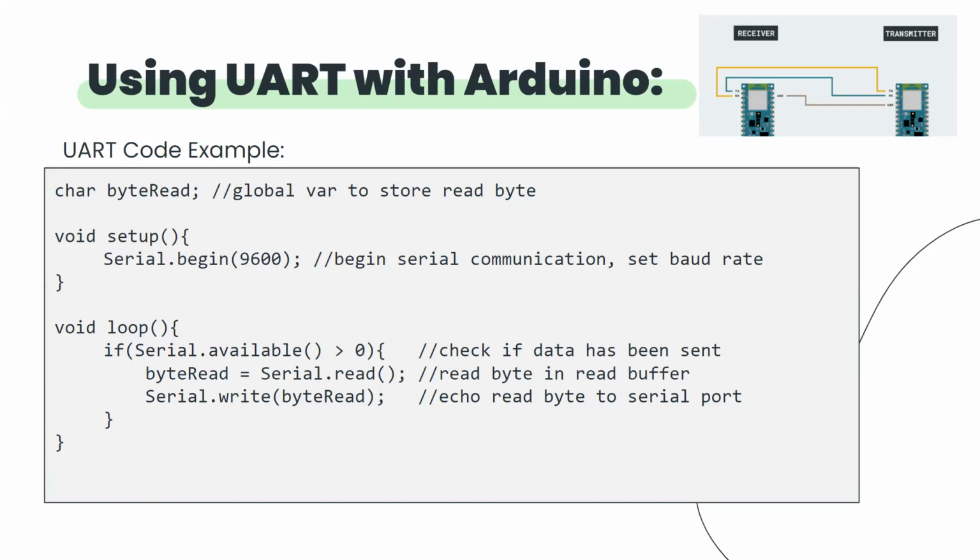Yeah, and Serial.write, that's sending it back to whatever it just came from, not the serial monitor, right? Yeah, so if you have UART communication, you have the RX and TX connected. It sends it right back to the TX. So it will send it out through the Arduino's TX into whatever thing you just received it from. Okay.